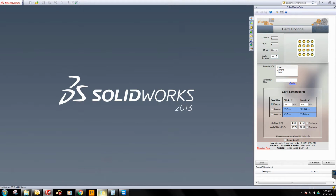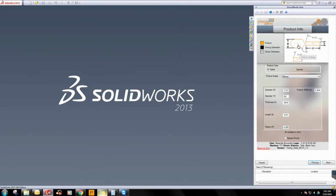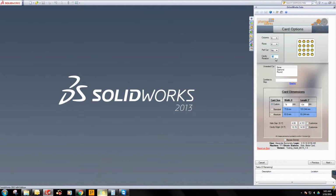So here's a cavity rotation feature. Let's go through that. The cavity rotation feature allows you to rotate that cavity about the center axis. So if I wanted, let's say, this tablet here to be at a 45-degree angle so that they would show up on the cards, I go ahead and select here, okay, 45 degrees, and go ahead and press enter. And you'll see all those values automatically changed.